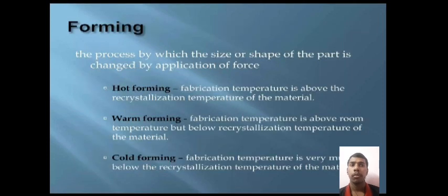Forming. The forming process is specially used to give the size and shape as we want to the pressure vessel. And there are some other types of forming too: hot forming, warm forming and cold forming. Within hot forming, the fabrication temperature is above the recrystallization temperature of the material. Now what is the meaning of recrystallization?